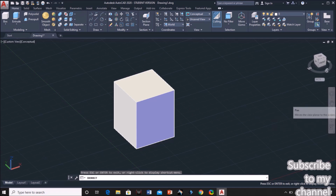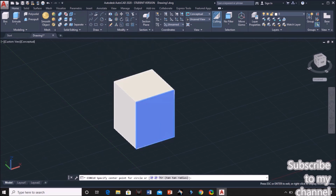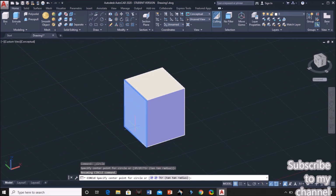Next I want to draw a circle here. I need to get the extrude option, and on this face I need to draw a circle and remove it. For that, give the command as circle, or else you can pick the circle option from here. I'm taking the center and radius option. On this face I need to draw a circle at the center.